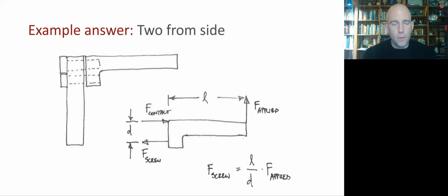So here's our free body diagram, and you'll notice that we've got this vertical force from the applied load. Oh, and I'm missing a vertical force over here as well. That should be equal and opposite to the applied force, maybe generated by friction from the contact between the 2 components. But the thing that I'm really worried about is that this applied force is going to create a big moment about, say, this point over here. And this length is a lot bigger than this distance.